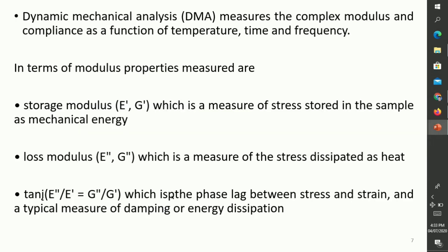Examples of sample deformation modes include fixed frequency oscillation, which may be single or dual cantilever, 3 point bend, tension, or shear sandwich, as well as resonant frequency oscillation, creep, and stress relaxation.